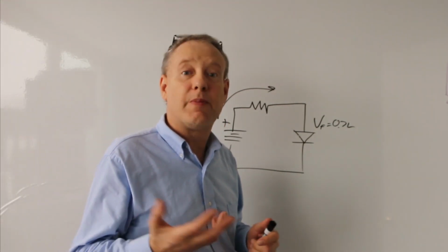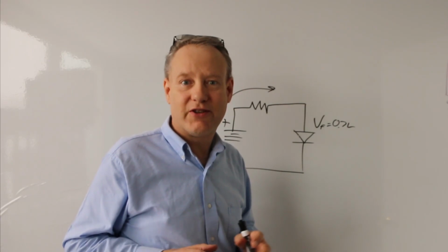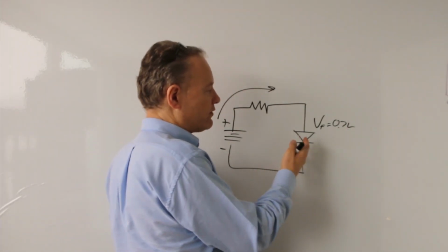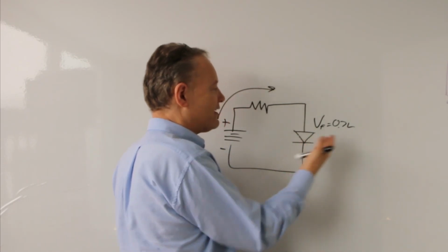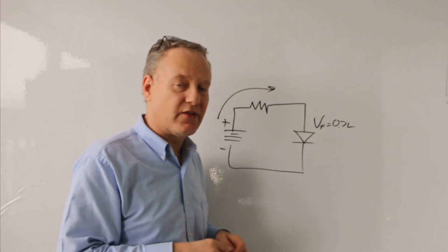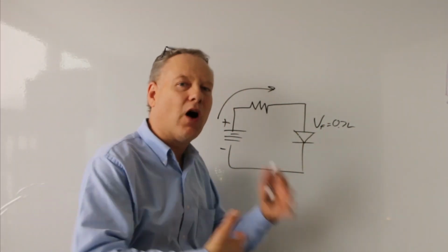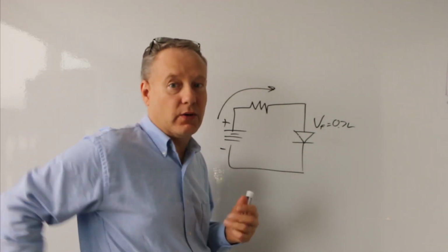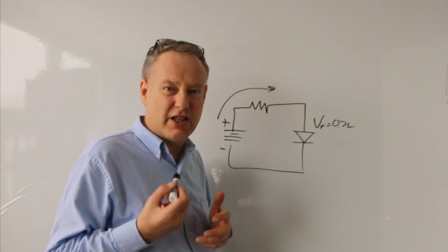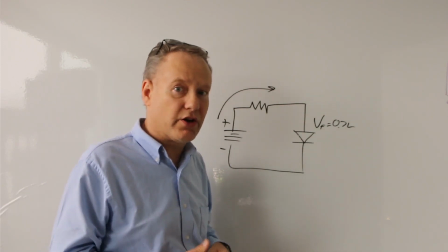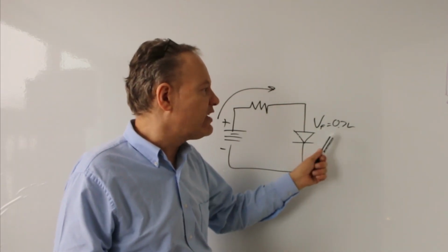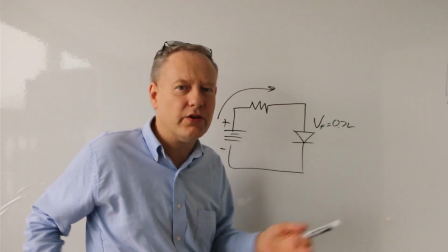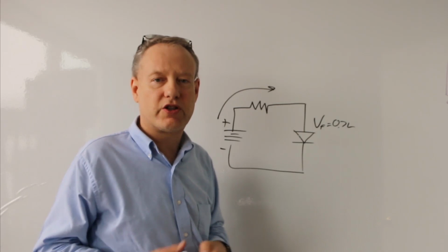If the people are trying to get out, you close the door. That's a whole other thing. But what's going on here is that to hold this open, it needs at least 0.7 volts to open up or to allow current to go through. Once it has that, it's always using it to allow current going through. And whether there's no current going through or a lot of current going through, it doesn't change the amount of voltage required to let the current travel through.